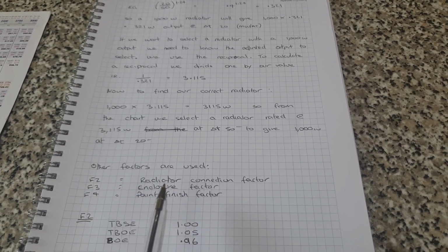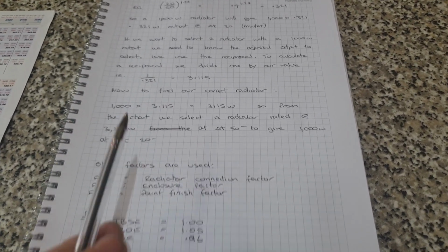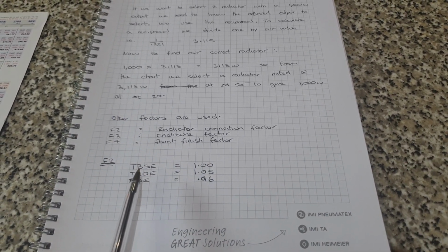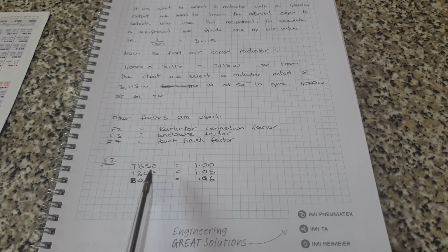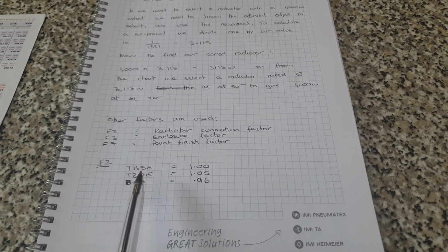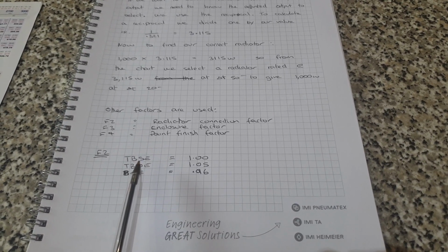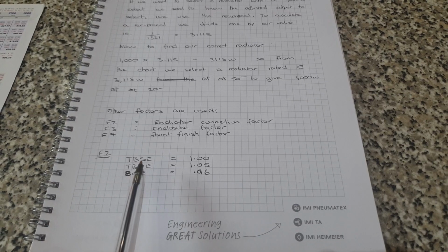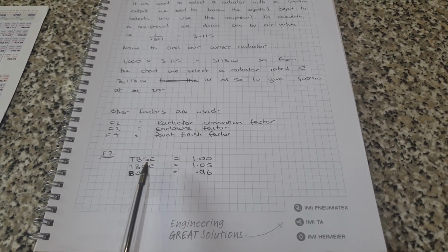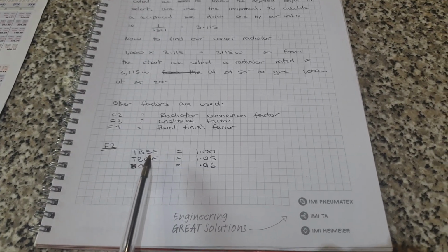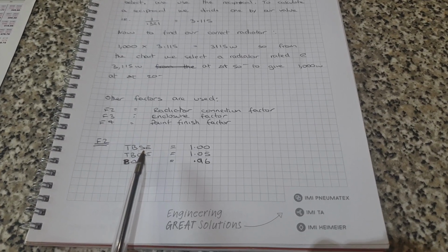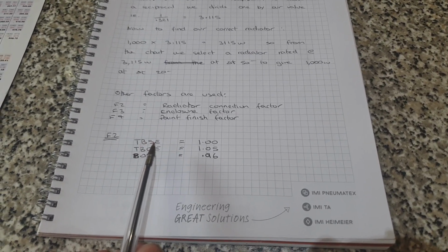Your F2 factor, radiator connection factor. This is quite an interesting one. The standard is top and bottom side, same end. Top, bottom, same end. And this is common practice here in Europe. In fact, in my flat in Estonia, my connections are done this way. So the TRV is at the top of the radiator, where you can actually get to it and turn it without bending over and cricking your back, which I never appreciated until I went past 50. And now I don't want to bend down to TRVs. I really like the system.